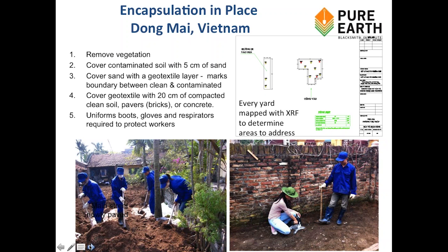At the same time, you want enough depth generally so that grass roots and any other plants they want there have room to grow above the contaminated soil. So it's not as simple as just spreading the dirt. You have to think about where the water is going to go and how this compares to the surface area of the homes and roads around the site.